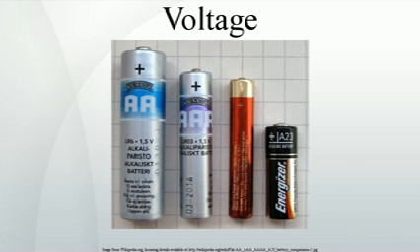Voltage is defined so that negatively charged objects are pulled towards higher voltages, while positively charged objects are pulled towards lower voltages. Therefore, the conventional current in a wire or resistor always flows from higher voltage to lower voltage. Current can flow from lower voltage to higher voltage, but only when a source of energy is present to push it against the opposing electric field. For example, inside a battery, chemical reactions provide the energy needed for current to flow from the negative to the positive terminal.